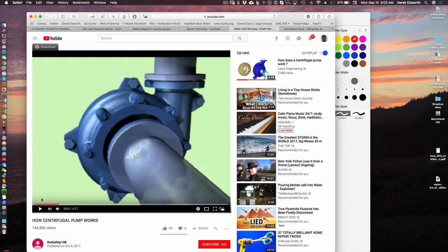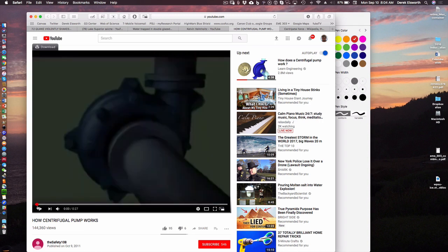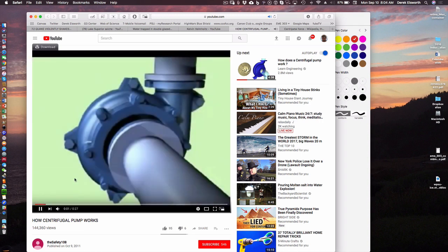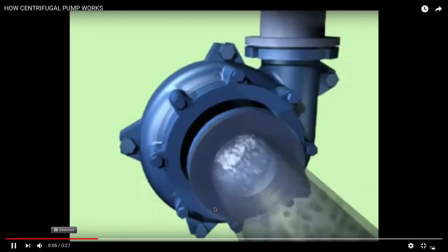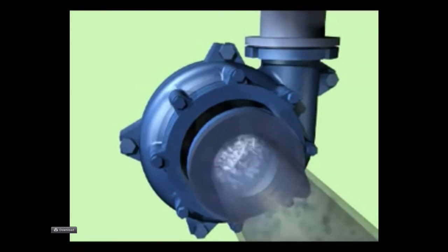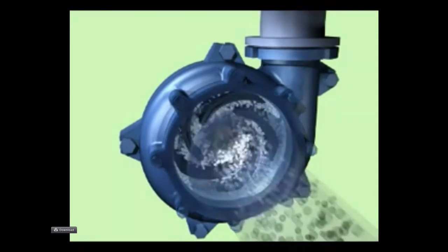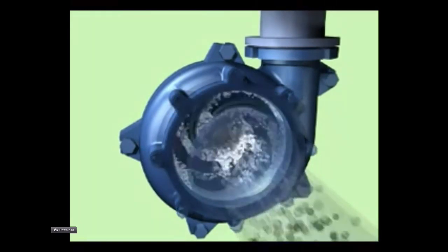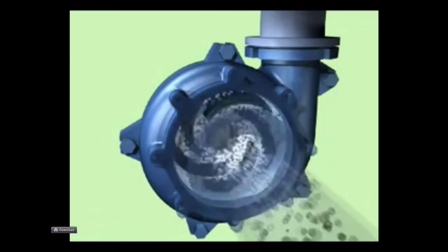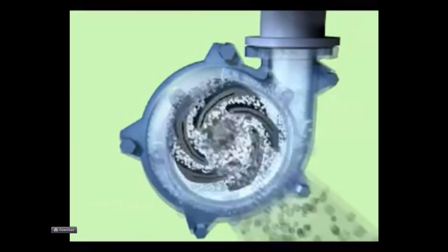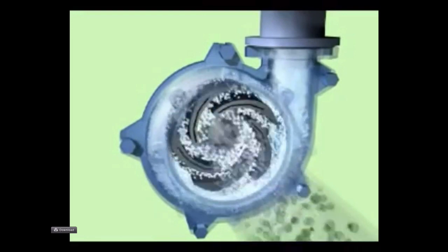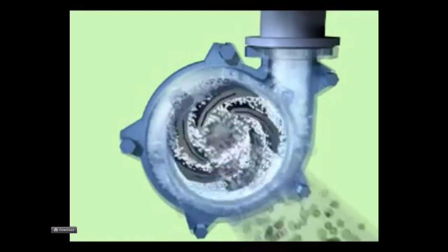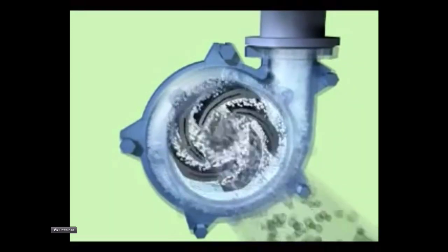So one of the other things that we'll talk about is accelerating fluids, but in the context of radially accelerating. And so the mechanism by which a centrifugal pump works is it has some blades that go around, they take some fluid and they push it out to the exterior, and the exterior goes up into this vertical pipe, which means that since it's moving it, then it sucks in more fluid along this longitudinal pipe that's supplying it.